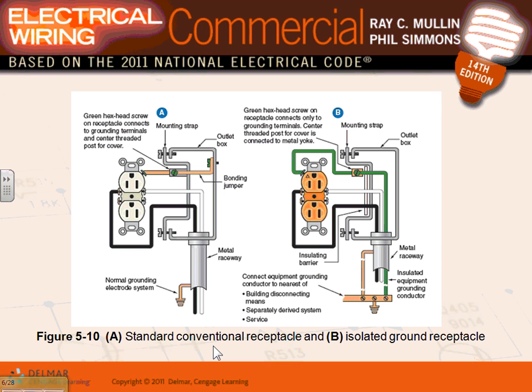You can also run two green wires and ground one to the box, but commonly the dirty ground will be through the pipe, and the clean ground will be through the fully insulated green conductor, like you see down here. Have you seen that done with Romex? Usually we don't even think of Romex when we think of these. You can't do it with Romex.